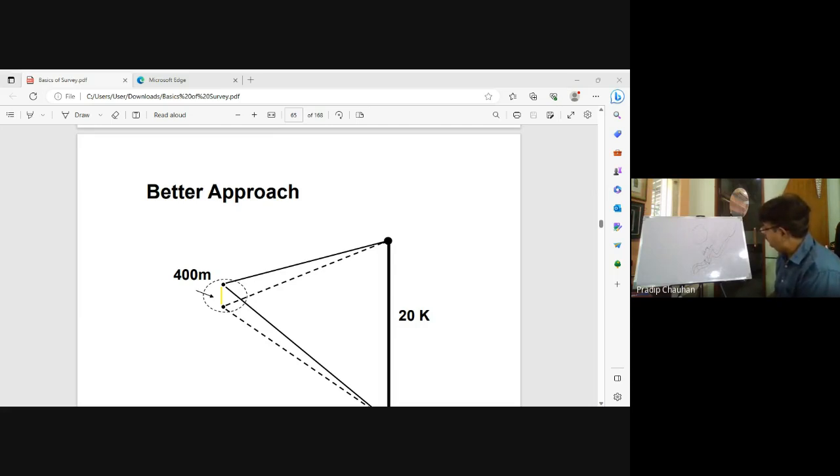So what we will do, again, we will fix up some control points using DGPS system on top of the road at certain intervals. Then say this is the terrain of the road in elevation. Here is my drone. The drone is a flying machine carrying certain weight. What kind of equipment does it have? One is RTK, then another is for navigation, another is a high resolution camera, and then one more is the LIDAR.